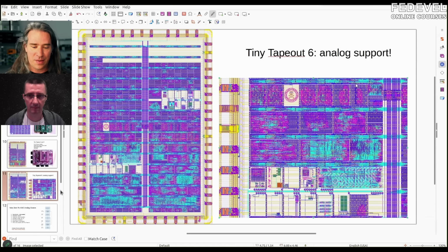So you have this thing, and in order for me to be able to give you something that you can make, because it's so complicated, you make one layer, you make another, there's masks, there's injection of charges, you're basically doping stuff and then masking and then etching, so there's a ton of rules to obey. Those rules are the process. The process development kit encapsulates those rules, as well as stuff that you could use to simulate. So all the SPICE models and all those things go in the PDK. It's this big package of all the rules, the models, and everything you need to be able to produce, in the end, a GDS file.